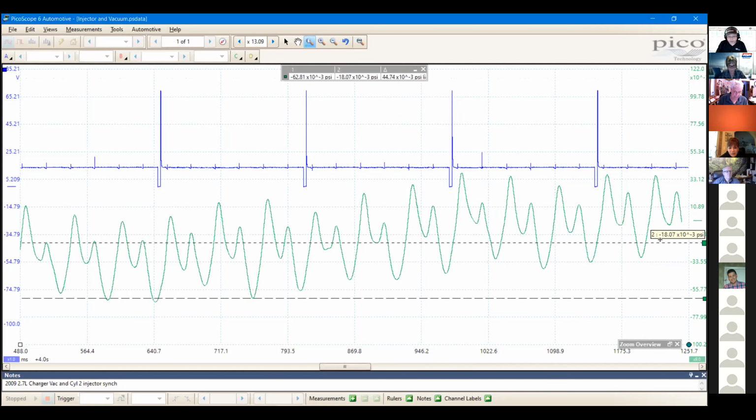6 suction events. I see less vacuum, more vacuum. Less vacuum, more, less, more. 1, 2, 3, 4, 5, 6. Every alternating cylinder is producing less suction event as compared to the other bank. The timing has jumped on this car. It's got a jump timing chain.